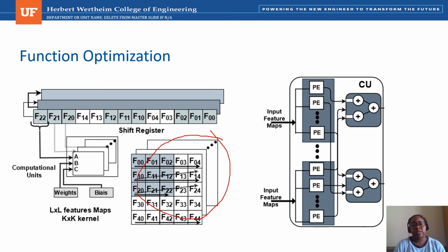In order to process data from those buffers, we use a ping pong protocol. So we first fetch the data into the first line buffer, the first on-chip buffer, and when the computation starts on this buffer, then the controller starts loading the data into the subsequent buffer. When all the data on the first on-chip buffer have been processed, then we switch to the next buffer and so on.